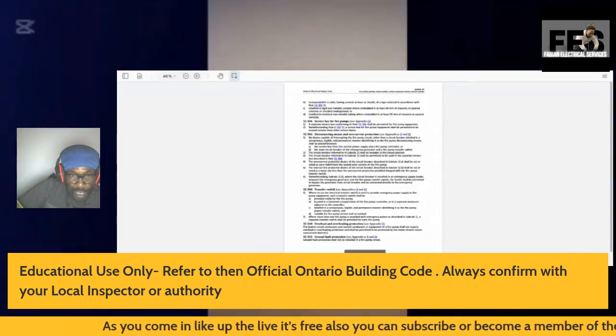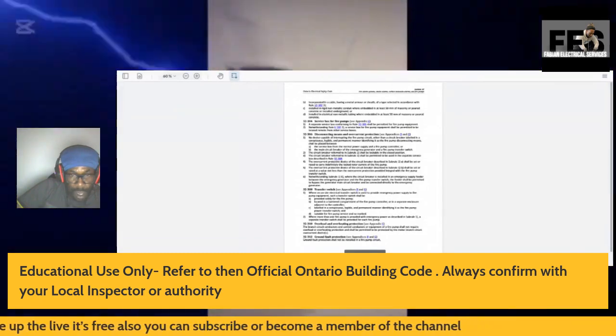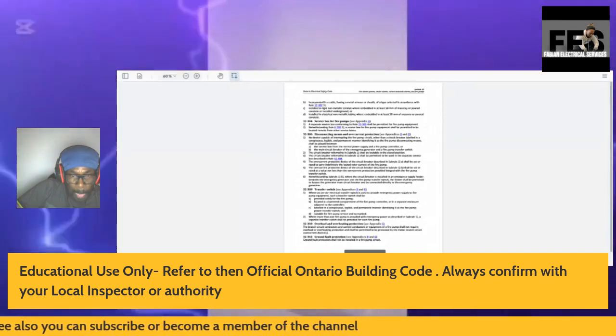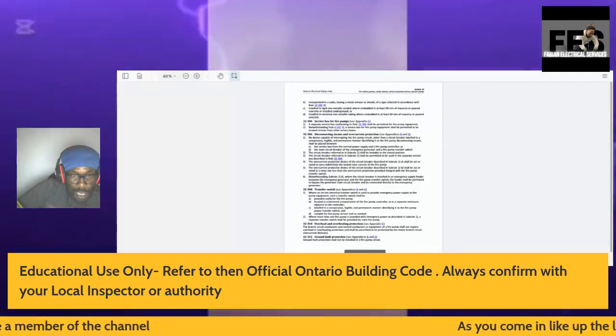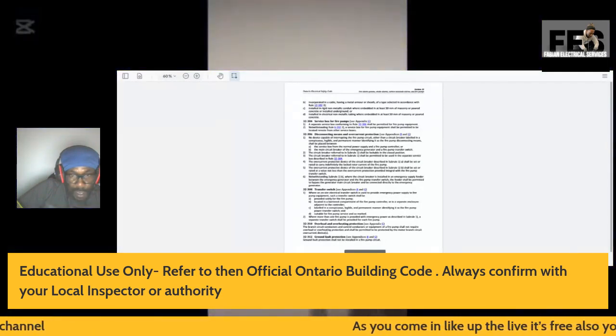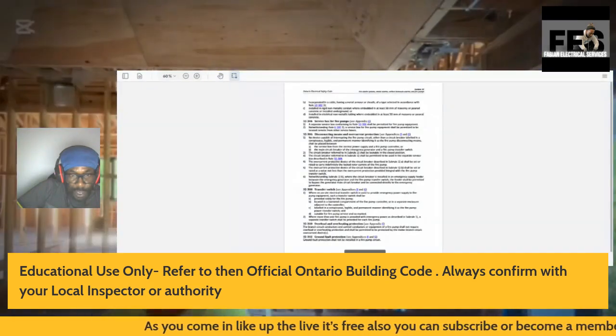The overcurrent protective device of the circuit breaker described in Subrule 1B shall be set or rated at a value not less than the overcurrent protection provided integral with the fire pump transfer switch.